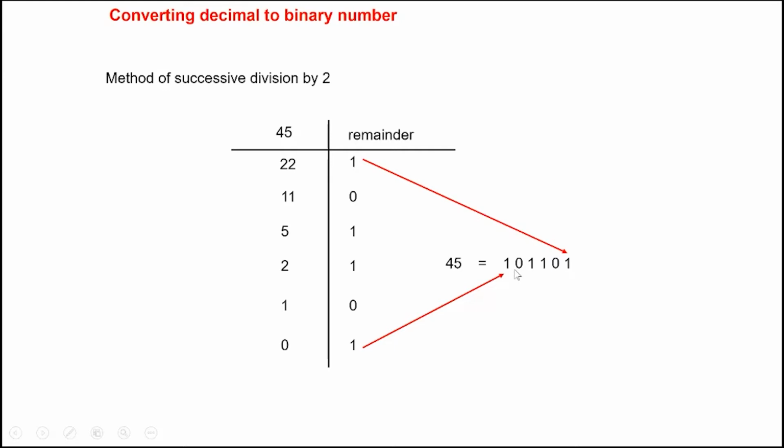So it's basically the same algorithm that we just saw earlier, by repeatedly dividing by 2. And through that we were able to figure out what is B0, B1, B2, B3. So this is a more compact, more systematic representation for doing the same thing here. And so we can convert any decimal number into a binary number by following this particular procedure.